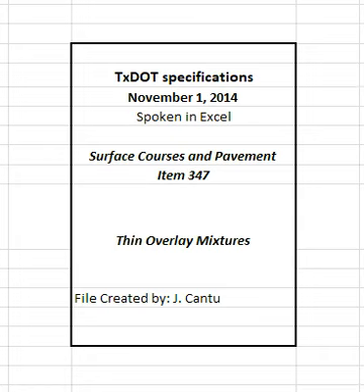The engineer will select subsequent lot sizes based on the anticipated daily production such that approximately 3 to 4 sublots are produced each day. The lot size will be between 500 tons and 2,000 tons. The engineer may change the lot size before the contractor begins any lot.